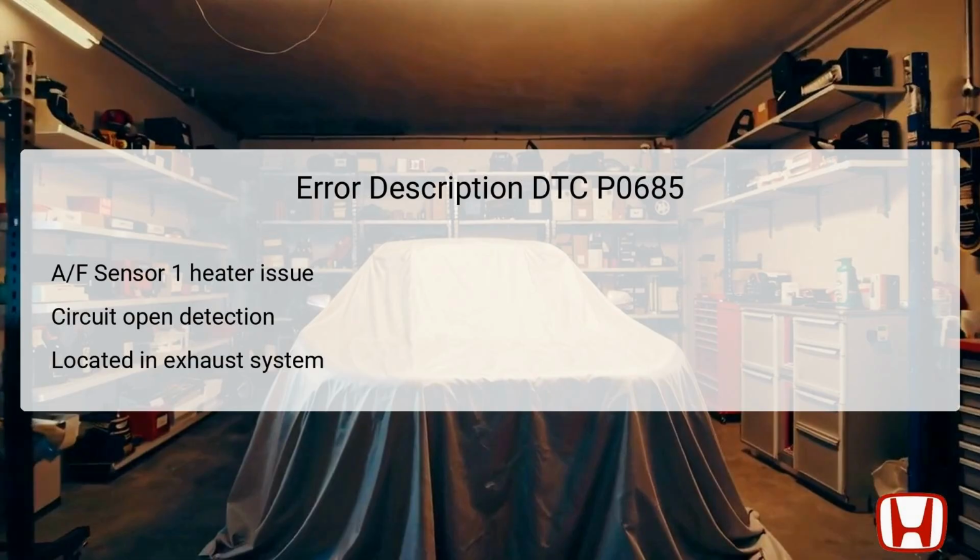When this DTC is set, it suggests that the heater circuit may be interrupted, causing the sensor to fail in providing accurate data to the powertrain control module, PCM. The PCM relies heavily on this information to manage fuel injection and maintain emissions controls. Promptly addressing this error is critical to restoring the vehicle's performance.